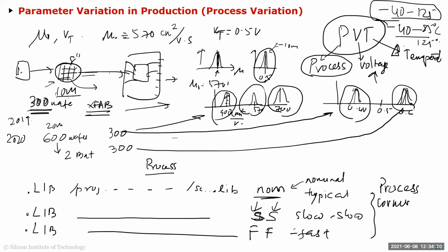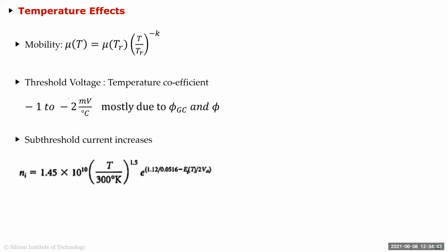They're called the corners. And the corner name comes because it's usually a matrix of process and temperature, or the binning. So you basically want to make sure that across all the corners of process, temperature and voltage, your spec is met within these corners, basically. Okay, like a temperature. So in semiconductor, just give me a second.